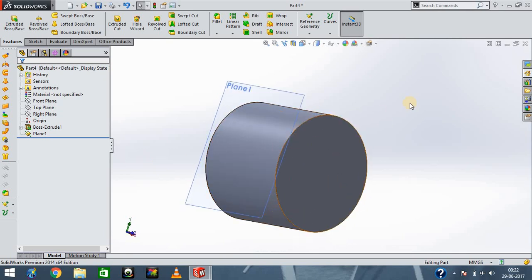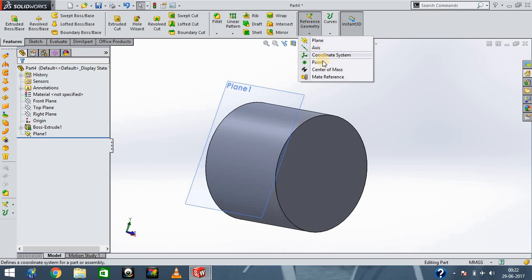In this way you can create an axis, coordinate system or point. You can create an axis taking reference edges, a line and a point, a plane and a point, two intersecting planes, 2 points, and you can create points with respect to points.